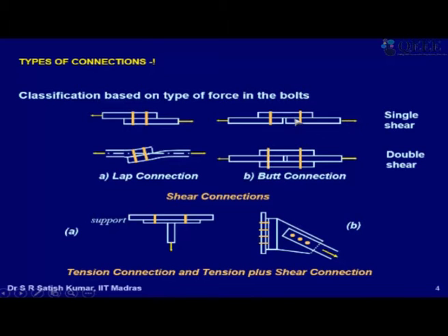Okay, so if I put two lap splices in series, but in the reverse direction. So this is my plate which is to be pulled, and this is the reaction plate, but I put what is called a cover plate like this, and then I transmit this force through these bolts. This may be one row of bolts or two rows of bolts, whatever, into the cover plate, and from the cover plate I transmit it back to the supporting plate. So I've apparently eliminated the eccentricity, but not really, because if I take a section through this middle part, I still find that this force has to go up and then go through that plate, and then again come down and become collinear, right?